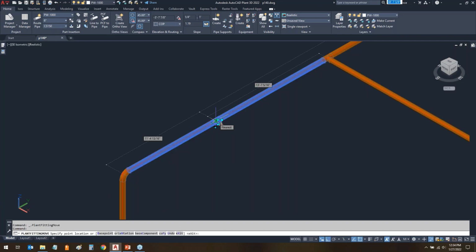This time they'll work as long as O-snap is turned off. If I try to leave O-snap on, it's going right back to the end. So turn off your O-snap to where there's not any O-snap. Select that move part. You get those dimensions and they'll work this time. You can come over here and say 10 foot.